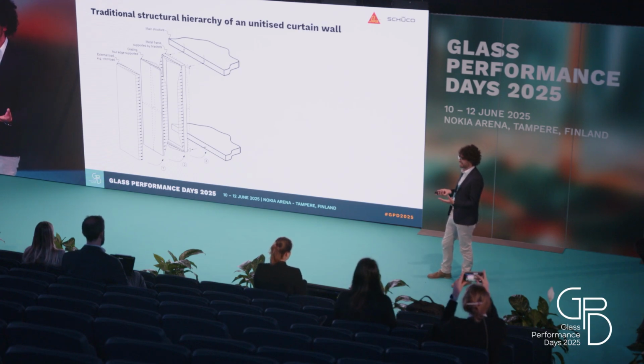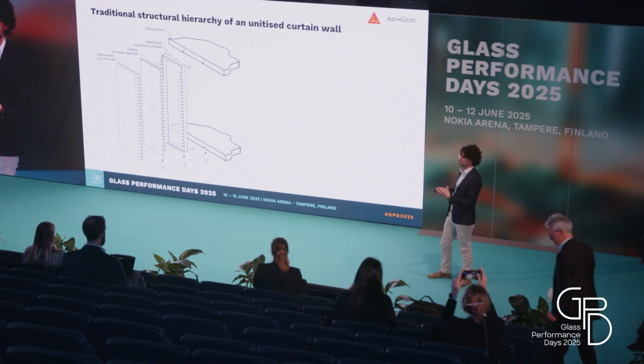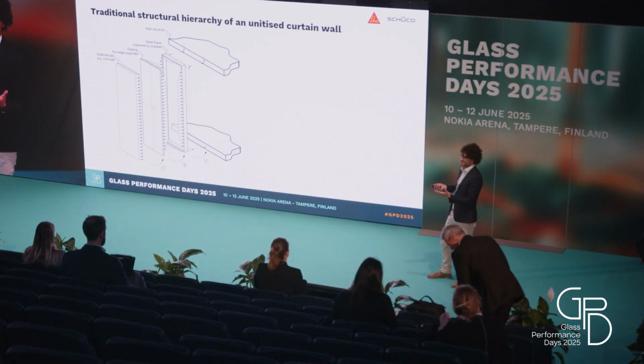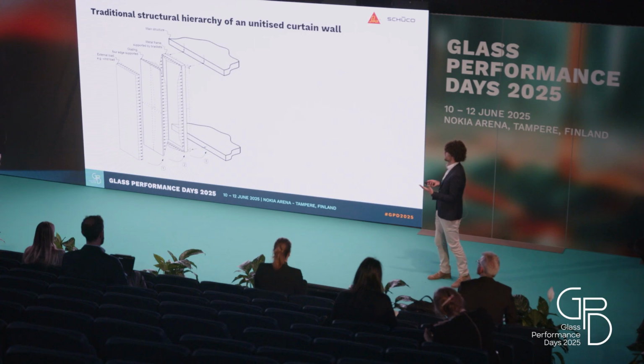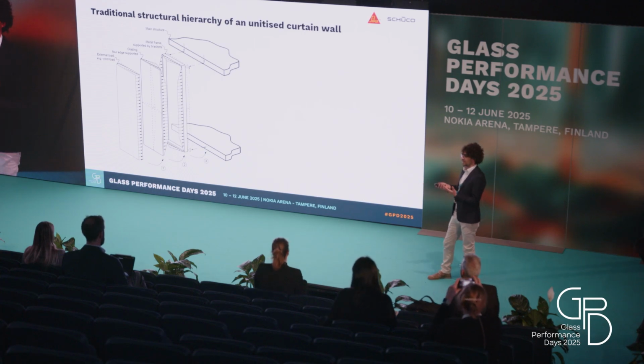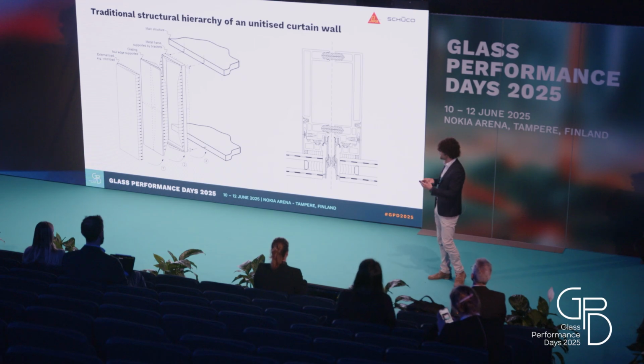And whenever you design an SG, so a structurally glazed unitized facade, you combine the two and you calculate the structural silicone, of course, to transfer some of the loads. But it's very rare in large fabrication of SG unitized facades to consider any partial composite action due to the interaction between the aluminium and the insulating glass unit. Of course, there are many typical sections.